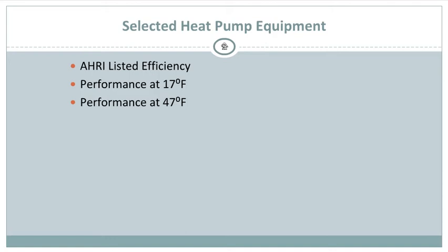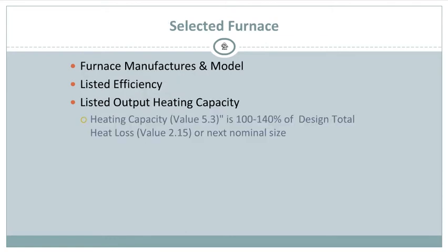Like I say, New Mexico is a great area for heat pumps because it rarely gets below freezing, especially down south. Again, depending on what size and how much your unit is, it'll tell you. You want to make sure that the unit performs well at 17 degrees Fahrenheit, which is the test when it's going to be at its coldest, and then at 47 degrees Fahrenheit. Okay? There's not much to heat pumps. It's just simply the testing and the installation, and that's it.